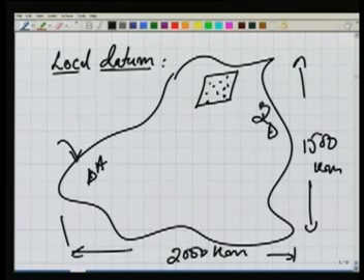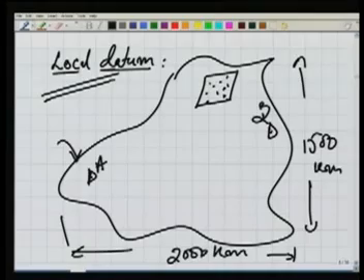Rather, I want to work in relative heights there. So what I can do, I can establish a local datum there. I need not go for this global datum. That kind of datum which you can establish locally, we say that is a local datum. For example, I can say there is a wall, and for this wall the height of this point is 0. The moment I say this is 0, that becomes my local datum.